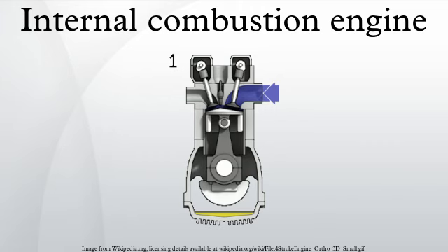For example, a real engine runs best at a specific load, termed its power band. The engine in a car cruising on a highway is usually operating significantly below its ideal load, because it is designed for the higher loads required for rapid acceleration. In addition, factors such as wind resistance reduce overall system efficiency. Engine fuel economy is usually measured in the units of miles per gallon for automobiles. The volume of hydrocarbon assumes a standard energy content.